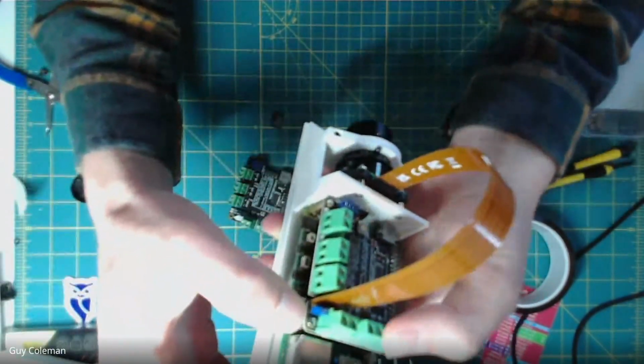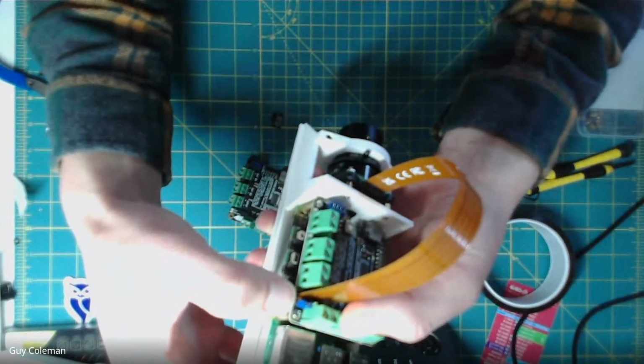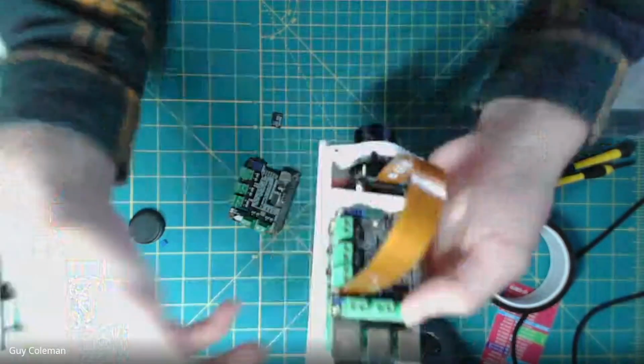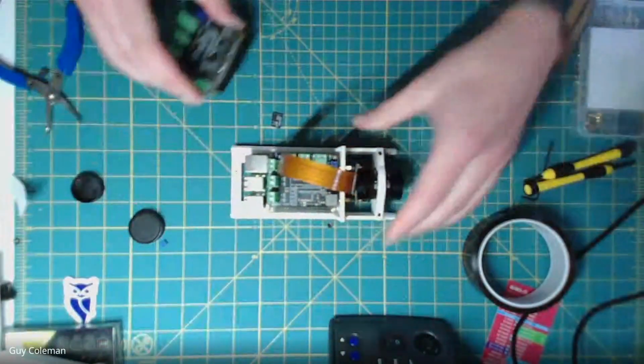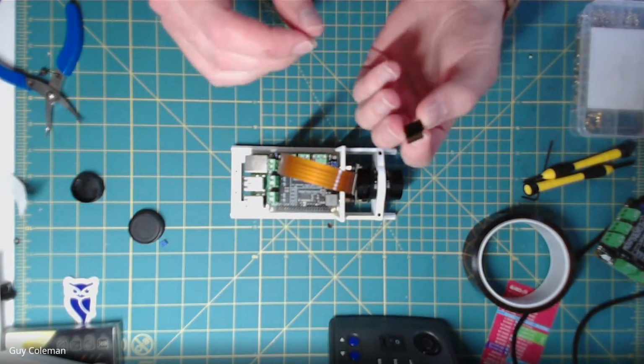And then finally, if, say, nothing of the outputs are being enabled, just double check there's a red light here and this jumper pin is on. All right, so that's pretty much the hardware done. The final thing is the SD card.